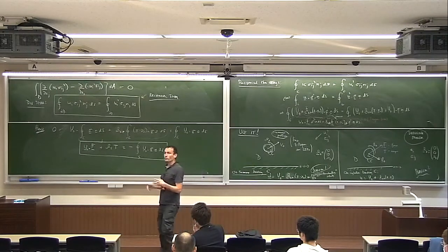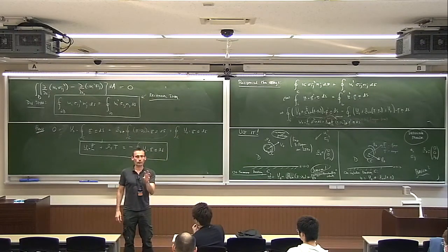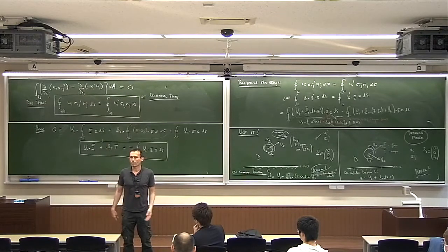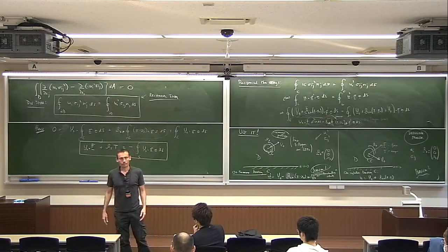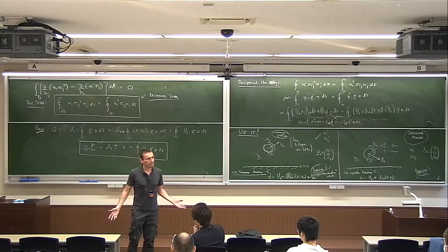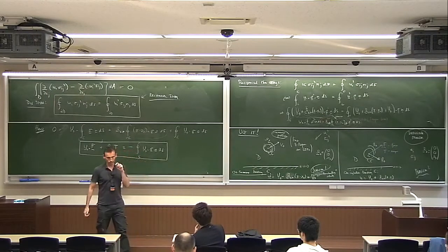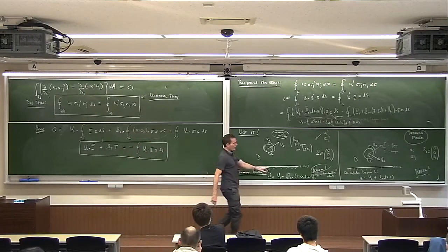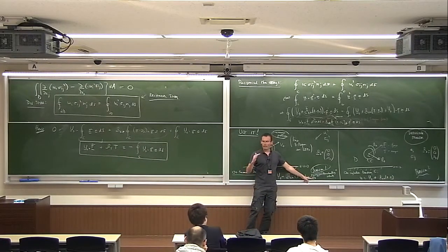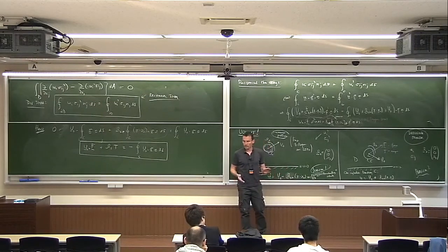So remember, if you're in ideal flow, suppose I had a cylinder in ideal flow and I just rotated it, nothing would happen, because it slips. If I've got a cylinder and I rotate it, or I don't even rotate it, but I've got a little surface that goes round, like a belt, it will drag the fluid with it. And so this is allowing me to have a kind of dragging of all kinds around the cylinder. Allowing me, by the way, to capture lots and lots of different physics.